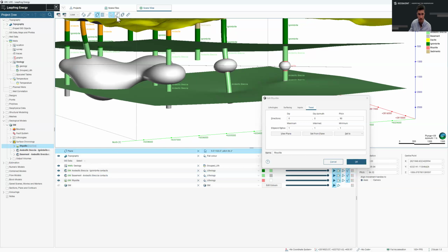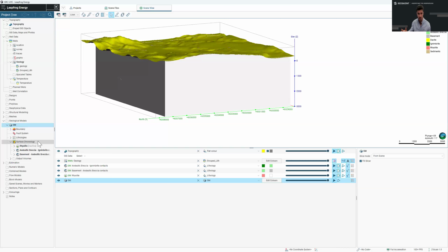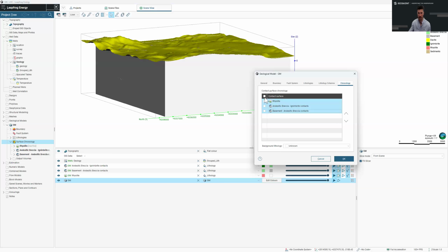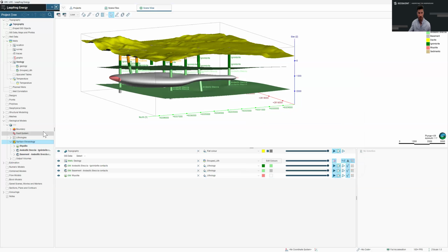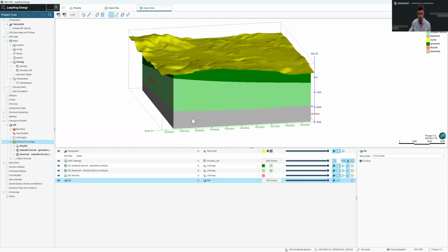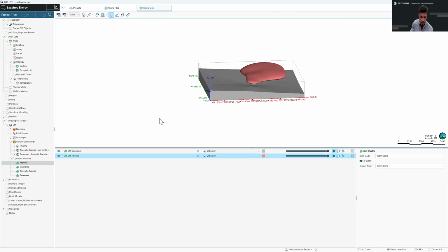Then we have our geologic model, which is still kind of an unknown volume of rock. To activate the surfaces that we just built and create volumes, we can double click the surface chronology, define the cross-cutting relationships. We can activate all of those surfaces, press OK, and then we have a representative geologic model. And that's a very, very brief introduction to Leapfrog, but these different geologic units are representative of your different rock types.